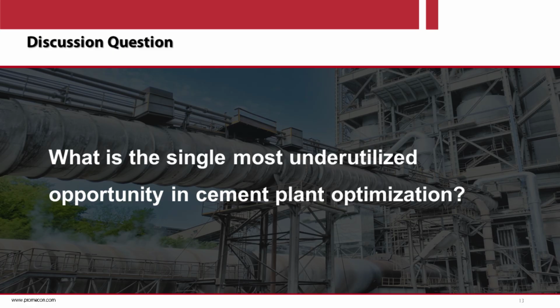The most important, underused opportunity right now for cement production is the use of SCMs, which require a highly reactive clinker. To make a highly reactive clinker, we need to master the combustion. We talked about that. So in the combustion operation, getting to 100% alternative fuel use and hopefully to a very high percentage of biogenic fuel use is the best opportunity we have right now.